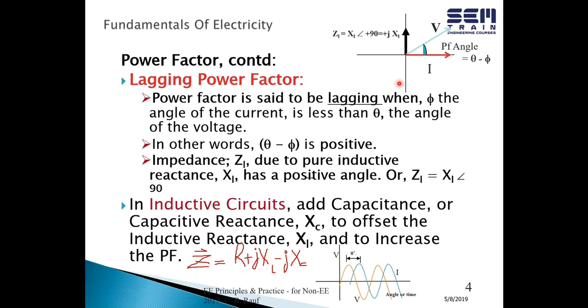And then we can look at the whole power factor business vectorially as well, and that's shown up here. So imagine yourself up here, looking down at these vectors. Which vectors are we talking about? The current vector and the voltage vector, because the difference between the current and voltage angles represents the power factor. The angle between the current vector and the voltage vector is the power factor angle. If that were 30 degrees, cosine of 30 is 0.866. The power factor would be 0.866 times 100, or 86.6%.